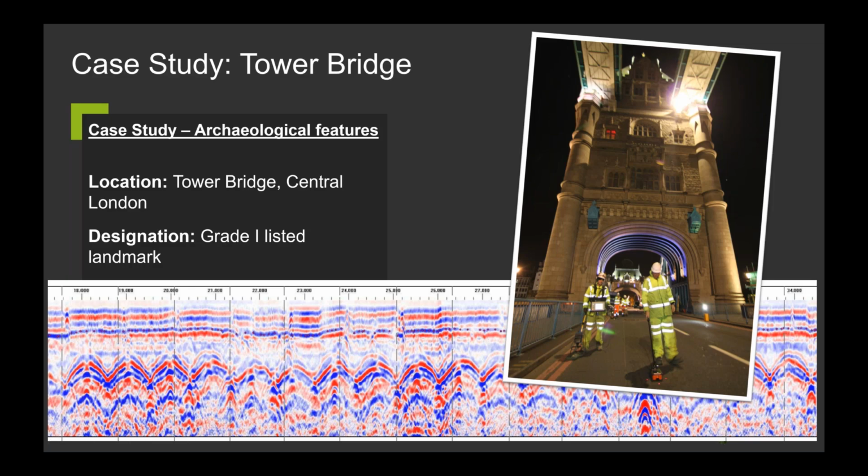And we know that there is a relationship between how fast the energy travels down to the bottom of that wood and back, so the travel time, and the moisture content. So the wetter the wood is, the longer it takes for that journey to happen, because the presence of moisture will reduce the speed of that energy, but it will also reduce the signal strength potentially. So we can also use the size of that reflection to help with our assessment.